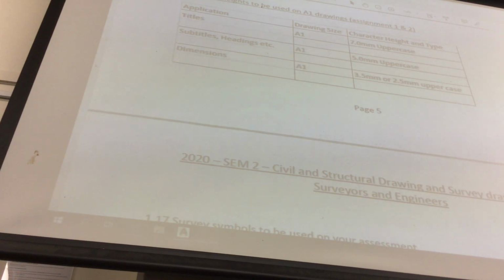And he doesn't want to know about dim offsets and all that sort of thing that you guys have learned. You're going to then have to go, okay, what did Roger teach me? Oh, that's right, the most common text is this height, the same as the arrow and the dimension text. What else did Roger teach me about the dimensions? Everything else is about a third. The other settings that we gave you last semester are about a third. I can't keep on giving you the answers because you get to an office and go, oh, I don't know what to do, I better ring Roger and find out what the best setting is, okay? It doesn't quite work like that.